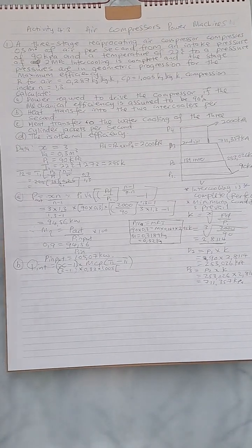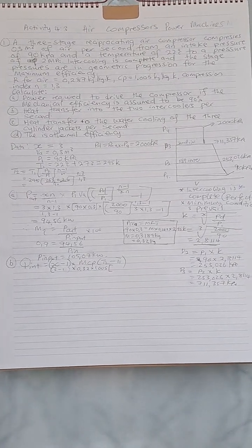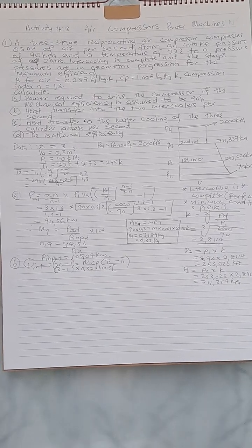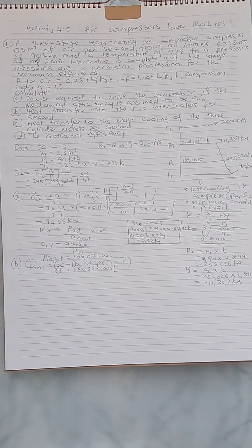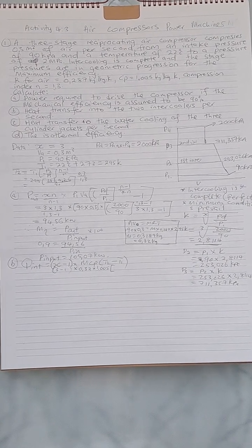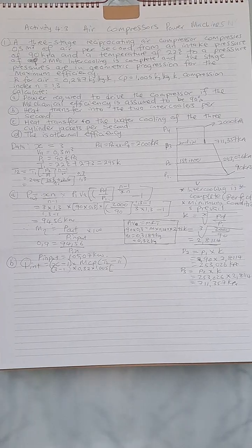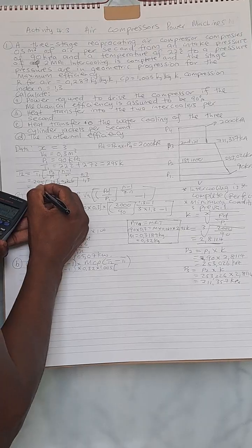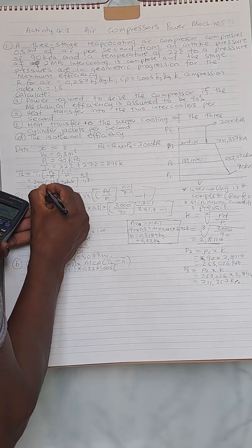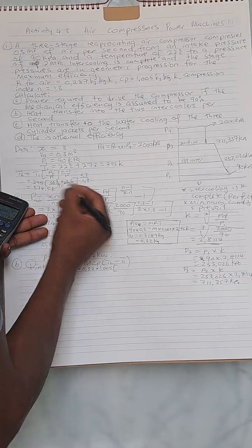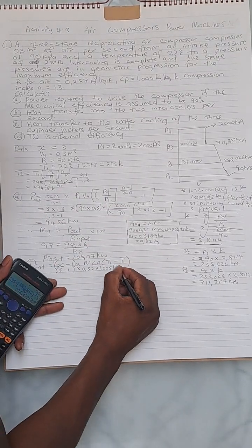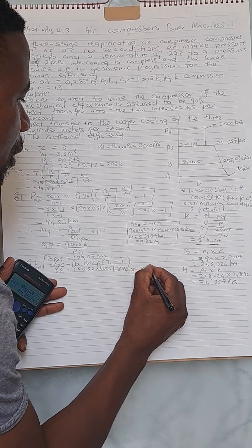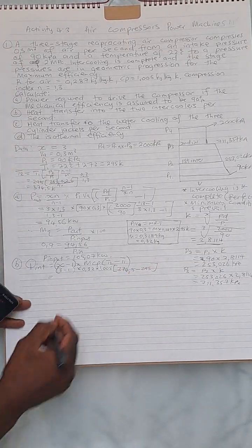So let's get our absolute temperature, which is 295 times bracket 253.026 divided by 90, to the power 0.3 over 1.3. So I'm getting my T2 as 374.5 Kelvin. So we come here, we substitute 374.5. Our T1 was 295. So let's get our answer.